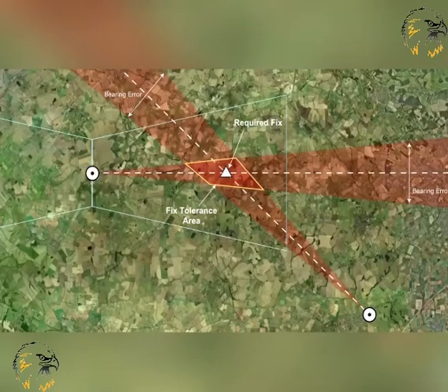Because the standard navigational systems have accuracy limitations, the geographic point which is identified is not precise, but may be anywhere within an area called the fix tolerance area, which surrounds the plotted point of intersection. The dimensions of this intersection fix area are determined by the accuracy of the systems that provide the information to define the fix. These are defined by ground station tolerance, airborne receiving system tolerance, flight technical tolerance, how accurately you can fly, and distance from the facility.